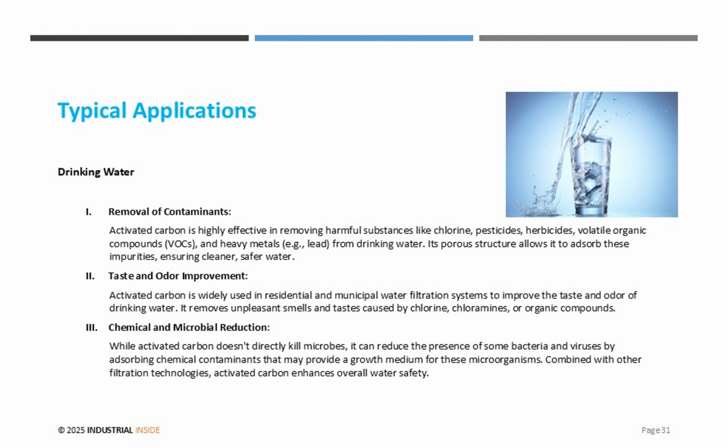Activated carbon plays a key role in drinking water treatment. It removes contaminants like chlorine, pesticides, VOCs, and heavy metals such as lead. It also improves taste and odor by removing chlorinated compounds. While it doesn't kill microbes, it reduces chemicals that support microbial growth, enhancing overall water safety.